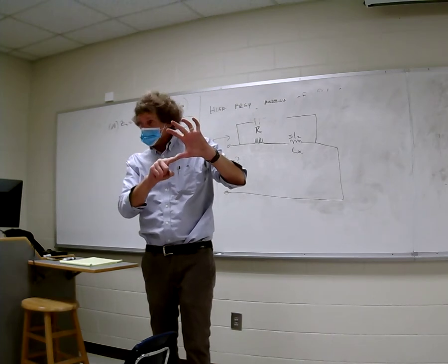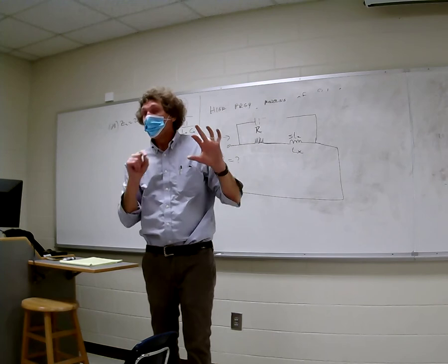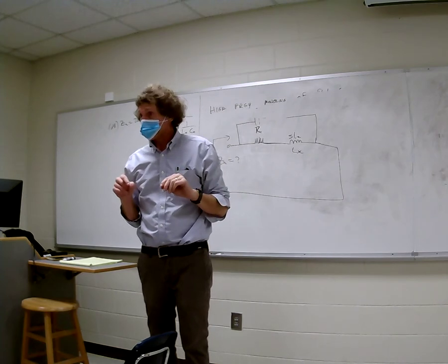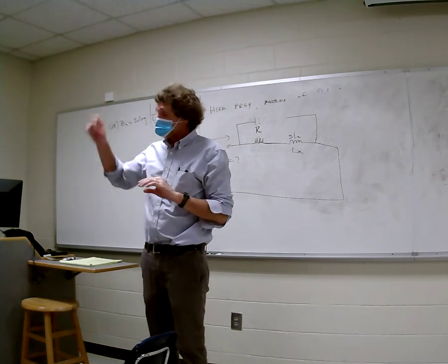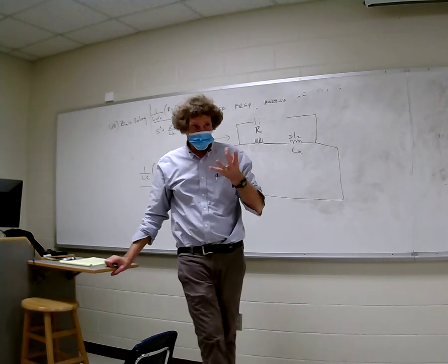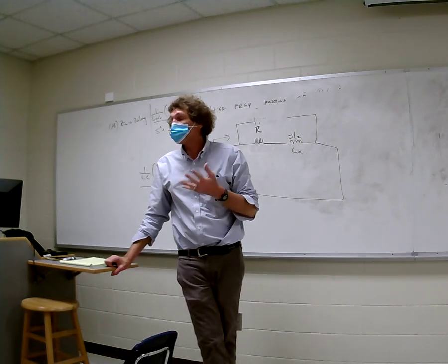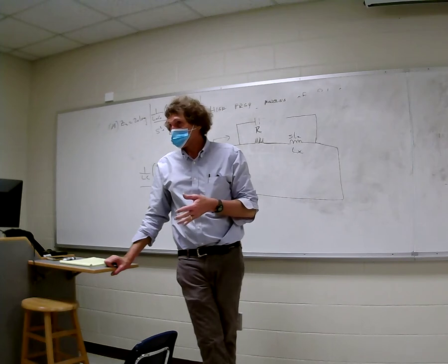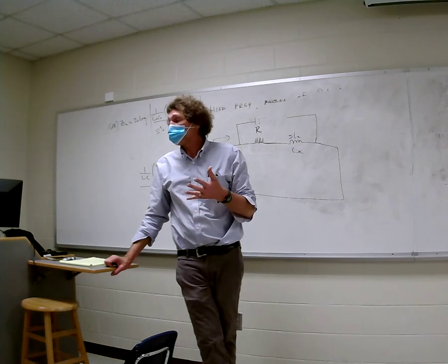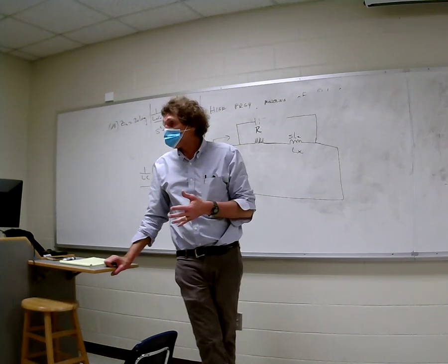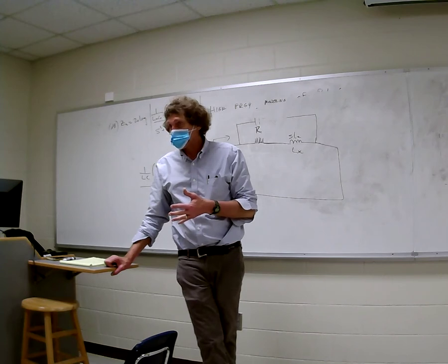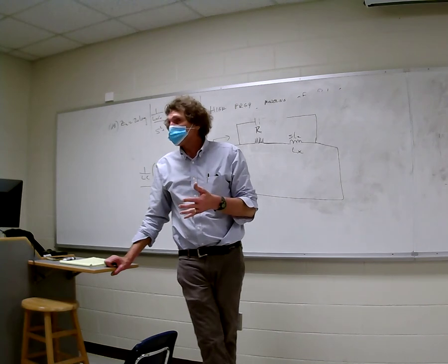Now, if you take that electrolytic capacitor and you try to go from a plus minus to a plus on bottom, minus on top, then they heat up like crazy. You can't have something where the actual polarity changes, it will not work. It'll be a disaster. Either they'll blow up or the resistance will be so low that it's basically overwhelming the effects of the capacitor. There's also a danger of explosion.